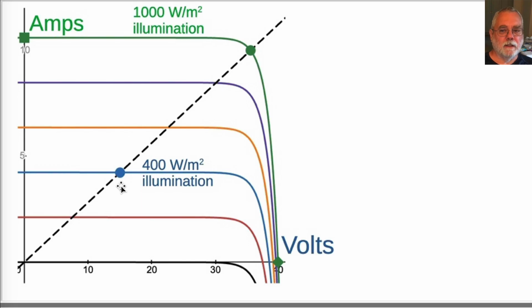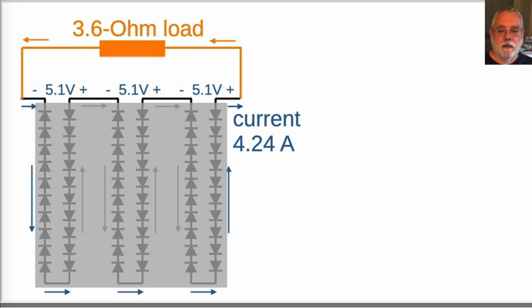In order to set up the case for a partially shaded solar cell, I want to stick with the fixed resistive load and not move to the right to the maximum power point for the blue curve, which a microinverter or DC power optimizer would do. We'll come back to that. Every solar cell is operating in the upper right quadrant of the panel IV curve, and there is no local heating when all the cells are shaded equally.